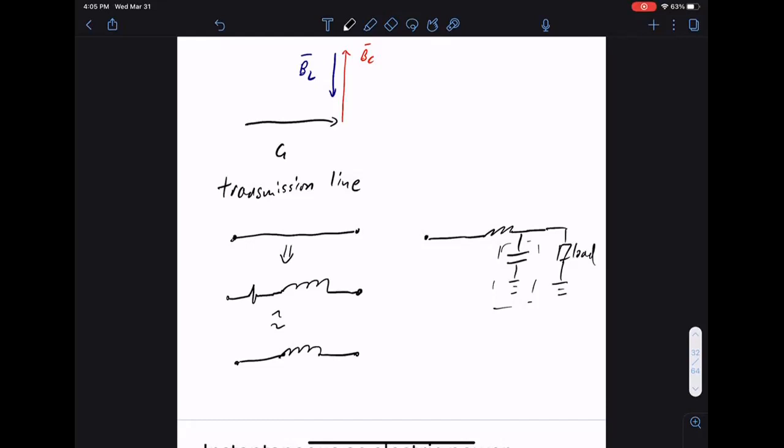I understand that. The power transfer for us, once it gets to the residential neighborhood, you're not limited by the power transfer capability of the line. You're limited by the voltage. So really for us, it's boosting voltage. We're not limited, especially when you see those capacitors, they're not trying to improve power transfer. It's really to say your voltage is low, so I need more reactive power to boost up the voltage.